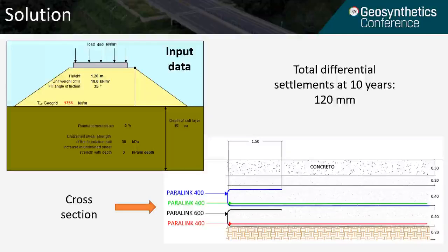Moreover, the design of the geogrid reinforcement was carried out using the elastic multilayer analysis. So given the thickness of the mattress and considering separately the effect of the static load and the instant effect of dynamic loads, it is possible to calculate the distribution of the horizontal forces in the whole mattress structure and select the appropriate geogrid for each layer.